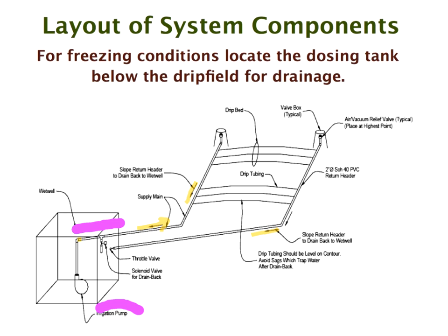And here they've got a solenoid valve, so you can open this up so that the water can come back down and drain back through. The solenoid valve opens when you switch off the pump. When the pump's on, it's closed, so it pumps up, and when the pump's off, this opens so it can drain back.